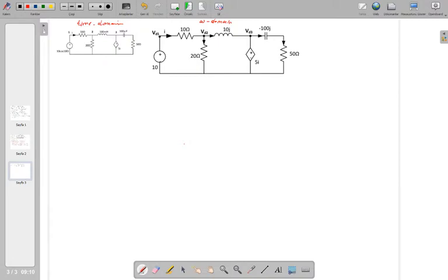So there is an independent voltage source here. We are in the frequency domain. That means all the independent sources are going to be sinusoidal functions. So this is one example of it. This time domain sinusoidal function is going to be transferred to the phasor of this sinusoidal function in the frequency domain. What is the phasor of this element? Vs is equal to 10 e to the power 0. Why is it e to the power 0? Because the phase of this sinusoidal function is 0. So therefore Vs is equal to 10. The phasor of the independent voltage source is 10.